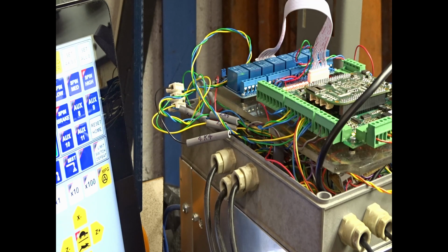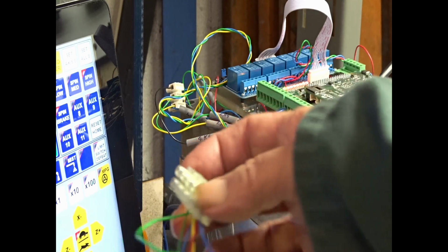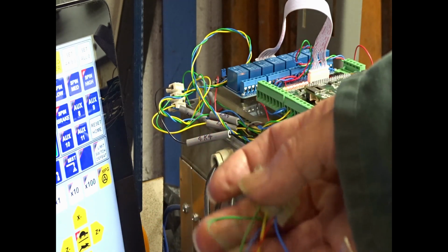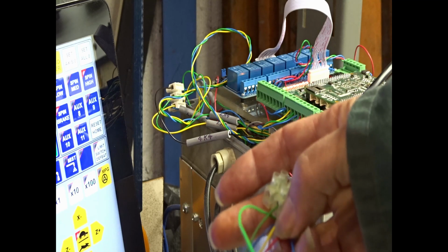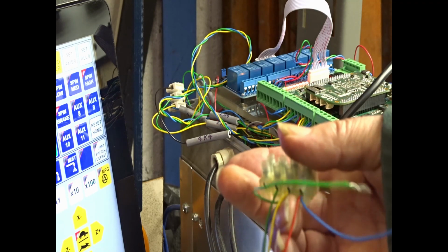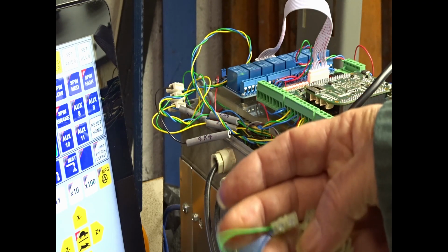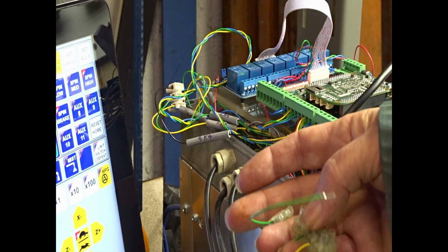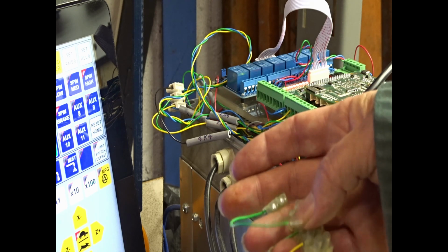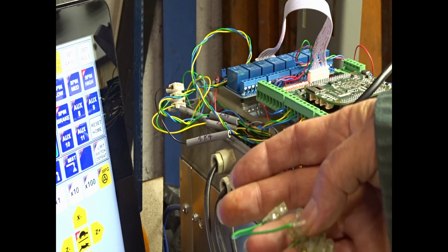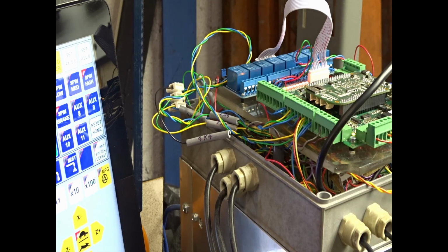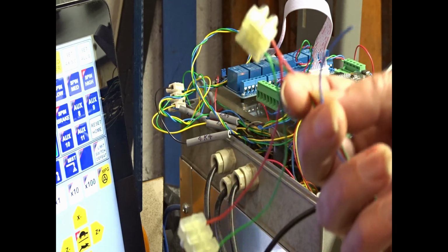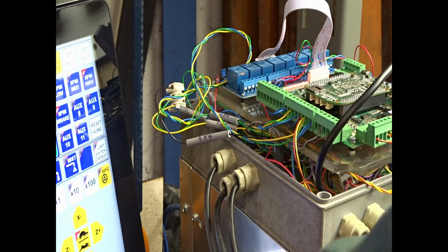I was able to feed out these signals coming out, which is the red one is ground, even though it's red. The blue is pulse minus. The green is direction and the yellow is enable. And then out of here I fed 5 volts, which was handy for checking that opto-isolator thing.